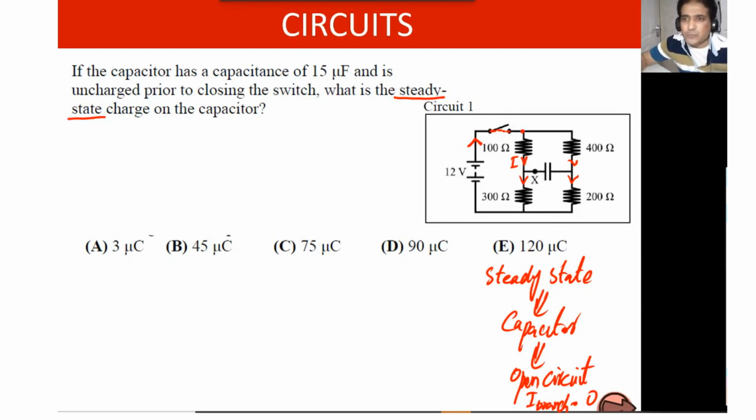So using this argument, now let's try to figure out voltage. You need to understand this resistance is 100, this is 300. So the voltage across this one has to be 1/4 of this one. Means you can divide this voltage into 4 parts. One part of the voltage is dropped across this one and 3 parts across this one.